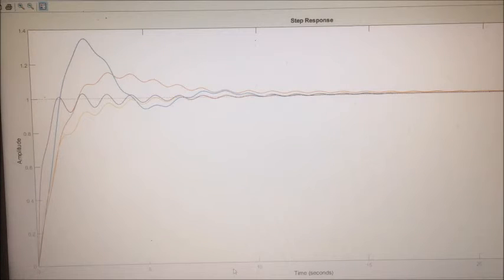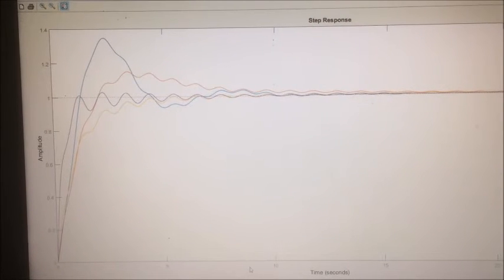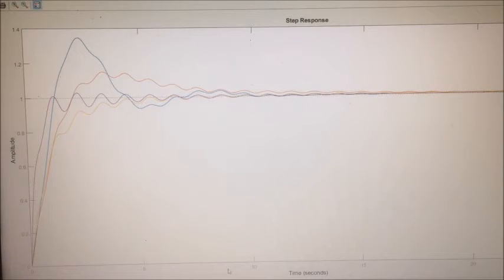So assuming the unit step for the reference input, the output signal of the gantry crane has been obtained. As you can see, the first try of PID tuning via the Ziegler-Nichols method has given me a reasonable time response of the gantry crane, while it almost eliminates the error at steady state.